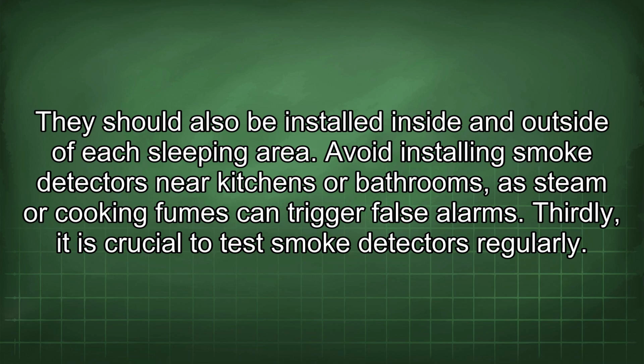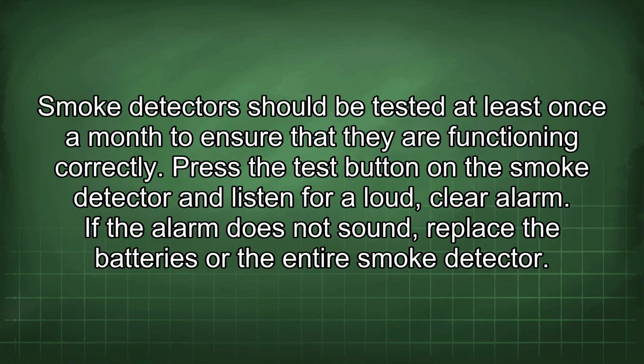Thirdly, it is crucial to test smoke detectors regularly. Smoke detectors should be tested at least once a month to ensure that they are functioning correctly. Press the test button on the smoke detector and listen for a loud, clear alarm. If the alarm does not sound, replace the batteries or the entire smoke detector.